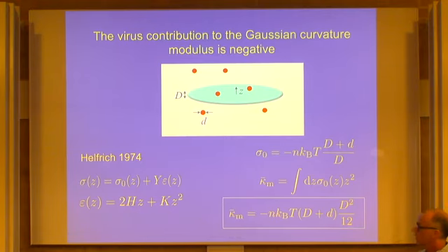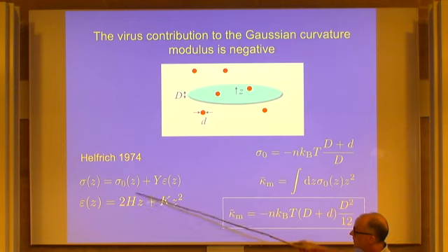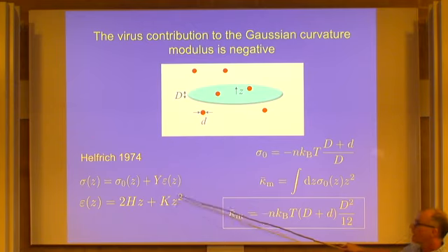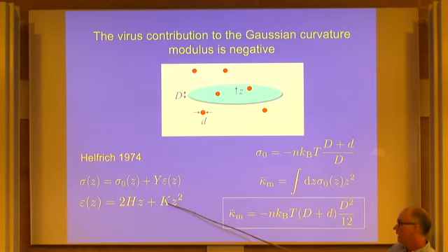So we can agree that if I take this and bend it, I don't want to break it, the outside is going to be longer than the inside. So that's this first term. But if we go to second order in the displacement, it turns out that there's a contribution of fixed sign, right? The first order term, it's longer on the outside or more area on the outside, less area on the inside when you bend it. But if the Gaussian curvature is positive, then the area goes up a little bit relative to the first term for both the inside and out.